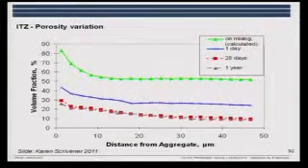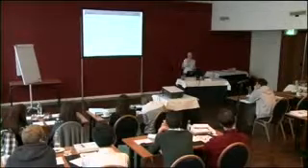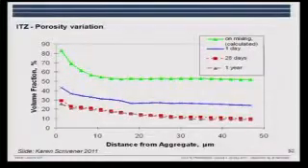You can make some calculations on the amount of material in the interfacial transition zone if you consider the width or the thickness of this zone, and then if you know the surface of the aggregates. And in a normal concrete, you can actually end up with half of the paste being in the interfacial transition zone. You can also consider that if you have a lot of this interfacial transition zone and it's interconnected, chlorides will not bother to go through the bulk. They will actually go through the interfacial transition zones then. Okay. There's a lot of discussion also on this.